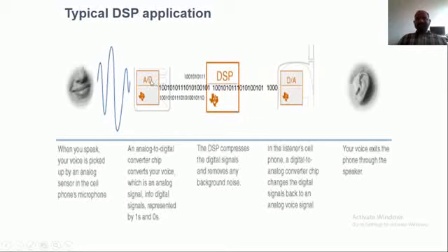As we have seen in the explanation, we have the switch which opens and closes at the highest speed, and that information is in the discrete format. The discrete information is compared with the comparator and converted into the digital format, that is nothing but the zeros and ones, the binary format. So when you are making a call to someone, your voice is analog information. This analog information should be converted into the digital format by the analog to digital converter. That is nothing but sampling: more samples are taken on your voice.